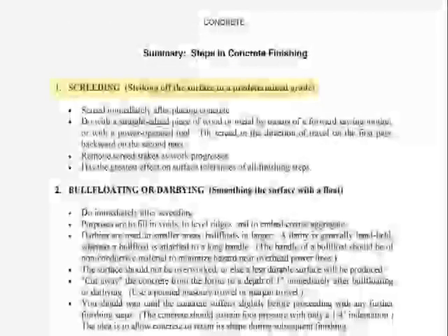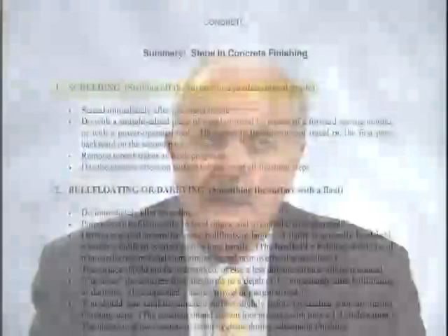grade. In other words, what we're doing is what most of us have seen or maybe done, is to drag a 2x4 across the top of the forms to get the wet concrete into the shape and into the form that we want it to be. The rest of the steps, next step would be bull floating and darbering, followed by edging and joining, and then floating, finally troweling and brooming. Need to know those and know those in sequence. Read over that, understand what each of those has to do, and you should do fine on the test.